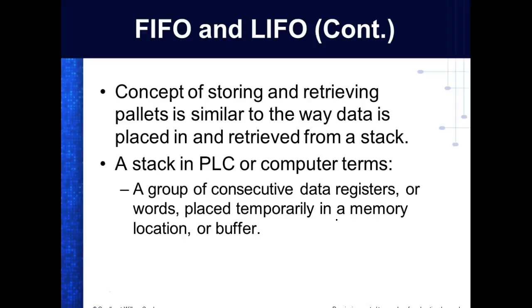But what I'm saying is that it's nothing but addresses. If you need to get into the stack somewhere, you don't have to use a push and a pull instruction. You could use direct addressing, right? Yes, it's addressable by all of them. We don't do that often, but I want to let you know you can get into the stack and get any location you want. Normally, we let the processor automatically control the address.